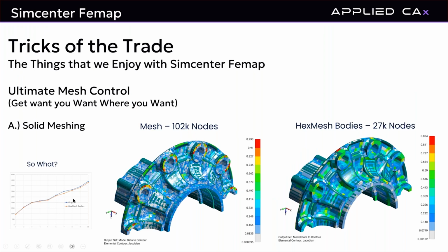This little graph here in the corner shows that when I'm idealizing models down and beating down the node count, usually for me, a good analysis means I'm rerunning the model dozens of times, it seems. It's never one and done. It's like 1, 3, 4, 5 changes of looking at sensitivity, looking at where it's going to go.